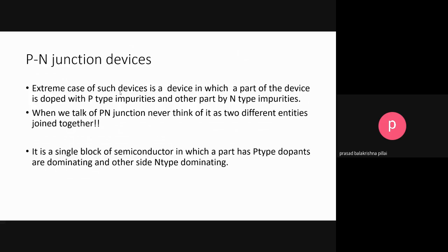One very important thing we have to understand is that it's not that we have one p-type semiconductor and another n-type semiconductor that you join together to make a p-n junction. It's never done like that. What you do is take a simple semiconductor block. Normally there will be prior doping, whether you take a wafer, Czochralski or grown otherwise. A wafer is normally doped either n-type or p-type. Let us say it's n-type, as in the earlier bipolar technology. Then part of that will be doped with p-type on the top, so it neutralizes n and becomes p. That is the picture you should have.